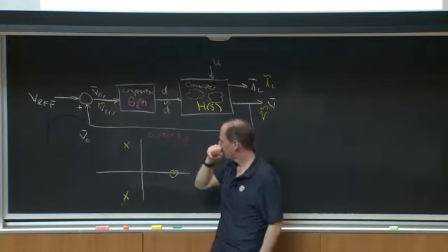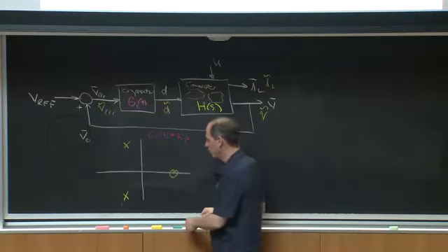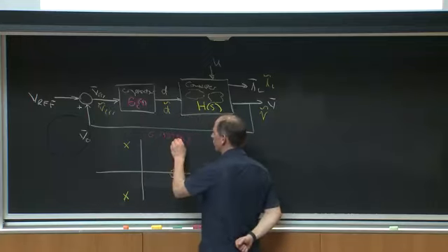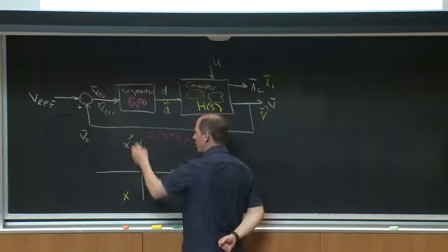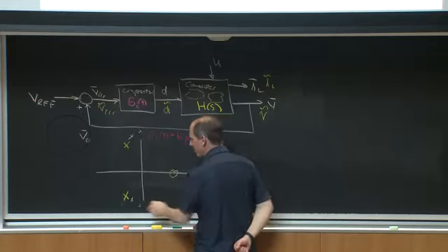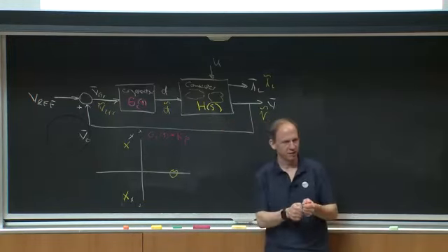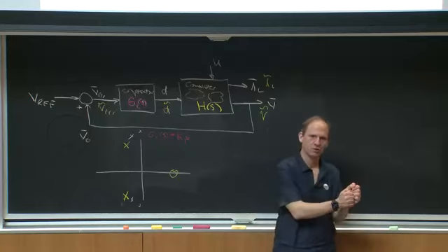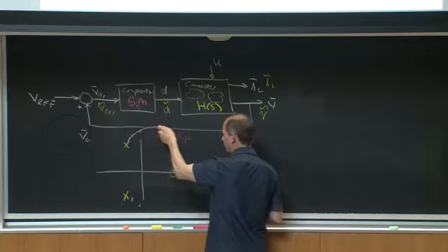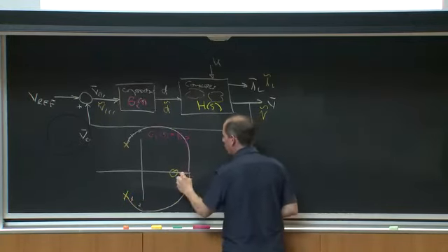Right? What I told you is, as I change values of GC of S, if I use a first value of KP, maybe my closed loop poles would move here. And if I took a higher value of KP, they'd move here. And if you do this, you can form what's a root locus and say, as I turn up KP, where do my closed loop poles go? And what this thing would do is it would do something like this. And then the poles would split.